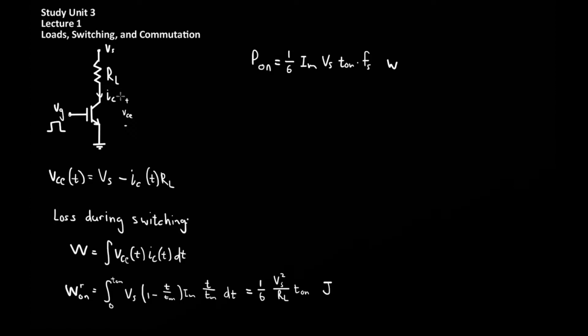In power electronics, switching is used to control inductive, resistive, and capacitive loads. Examples of inductive loads are things such as electrical machines, transformers, solenoids, and relays. When these types of loads are turned on, there is typically a very high rush of current, which is called the inrush current. This inrush current needs to be controlled in order to prevent it from damaging the equipment.